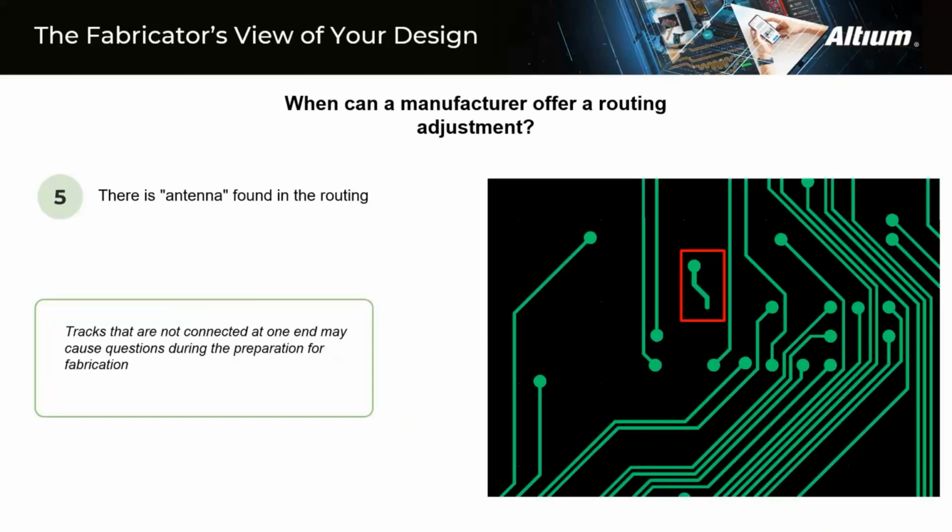And finally, the last point that I would like to mention is the so-called antenna. There are traces that find their way into the design that are not connected to anything at one of their ends, which will act as an antenna.